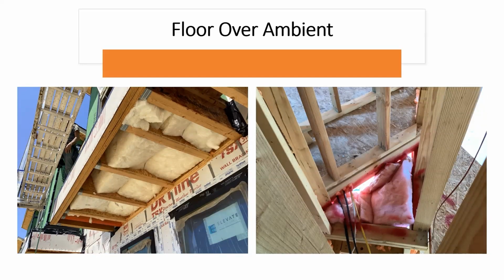So large gaps on the left, not fully filling encapsulated on the right. Even though the one on the right looks to be in conditioned space or facing a conditioned space, it's actually in a dead space that's not capped at the top. I did this inspection. I took this photo. The top of this chase was not capped, so we were asking them to cap that, as well as now you have to put air barrier behind all the interior walls and the chase walls.